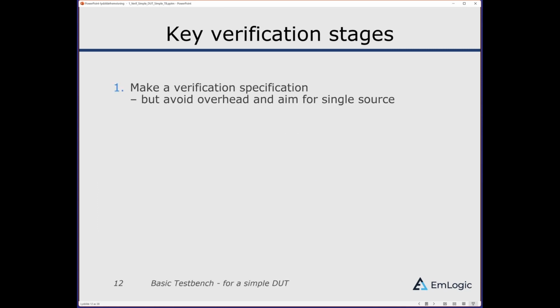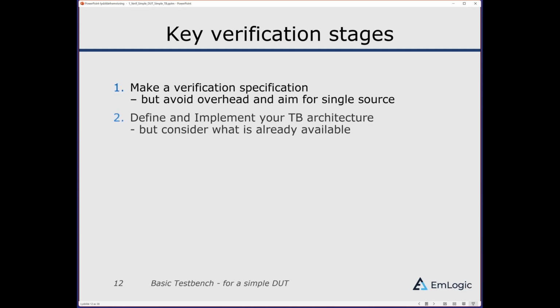This is an interrupt controller. It has a clock and a reset, a simple bus interface, which I'll come back to, n interrupt sources, and the resulting interrupt to the CPU. So let's say it's a really dead simple module. It has some registers. For every single interrupt input, it has an interrupt enable, clear, trigger, and a status